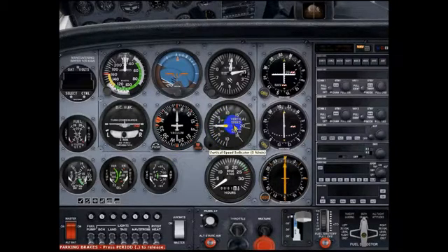The sixth one that I want you to be familiar with is the vertical speed indicator. The vertical speed indicator tells the pilot how fast the pilot is climbing, if it's up or descending, and we have our up marker and down marker in feet per minute. Again, we have 100 feet per minute, so we add 20.